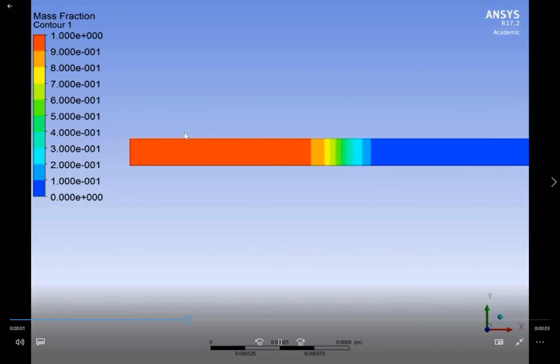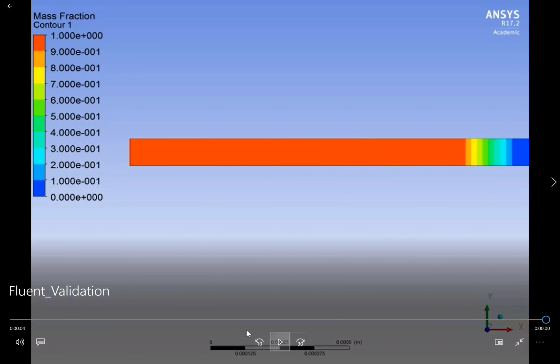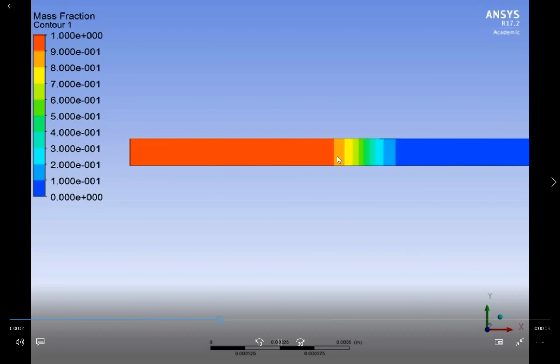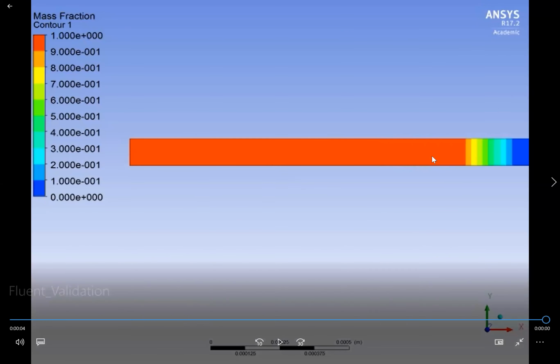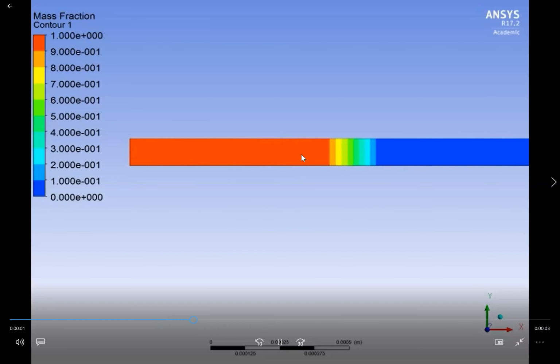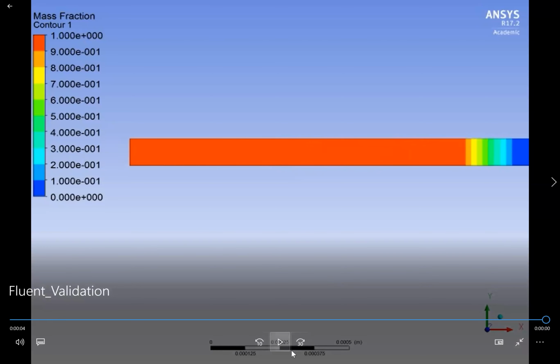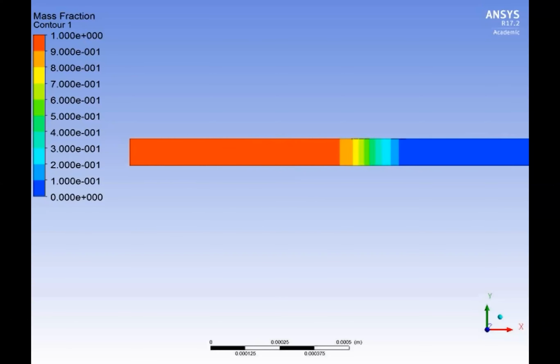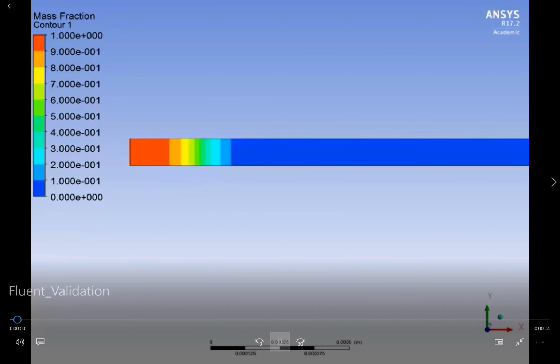But the red region is indicating water. The blue region is indicating ice. The rainbow region is indicating a mushy zone that tells us that we are part liquid, part ice. And as we're applying heat to the left-hand side, we're seeing our water region is beginning to grow outward and propagate. And it almost looks like a caterpillar moving along. So this is a fully explicit scheme.